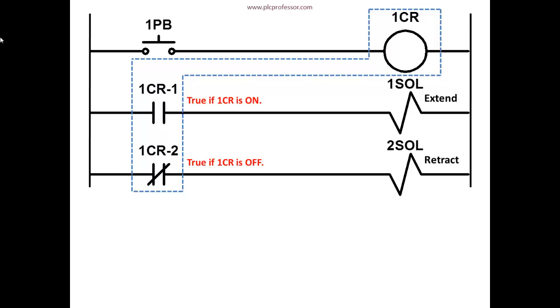This is an electrical relay ladder diagram. The left and the right vertical lines are power rails, as we explained. They supply voltage to the three individual circuits, and again, they are totally independent of each other electrically, but not logically. The contact relay 1CR connects these three individual circuits together logically.